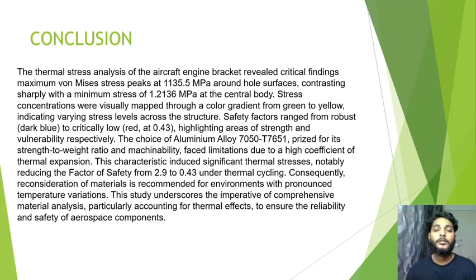The choice of aluminum alloy 7050/T7651, prized for its strength-to-weight ratio and machinability, faces limitations due to its high coefficient of thermal expansion. These characteristics induce significant thermal stress, notably reducing the safety factor from 2.9 to 0.43 under thermal cycling.